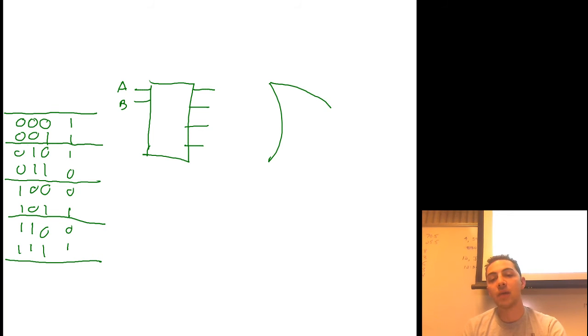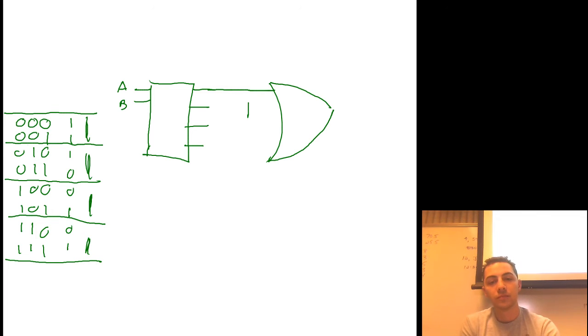So what am I going to have? I'm still going to have a big OR gate here. But I'm going to look at each group of 2 and make a little mini circuit out of it. This first circuit is just always 1, so I'm just going to hook it up right there. This next circuit is C bar.